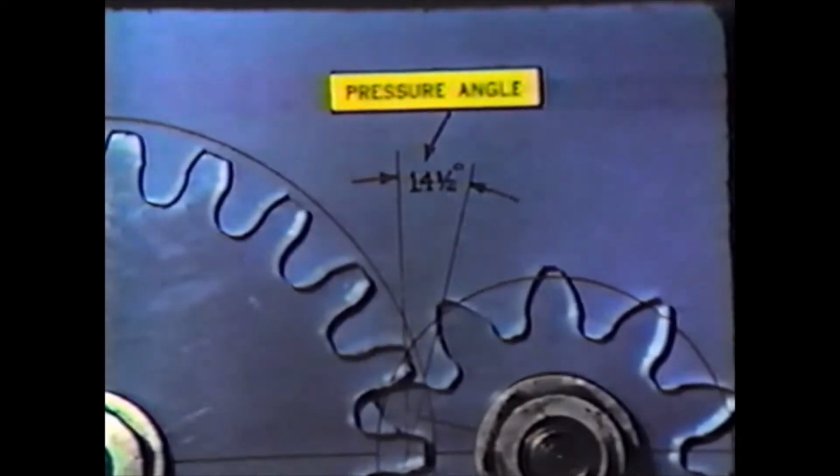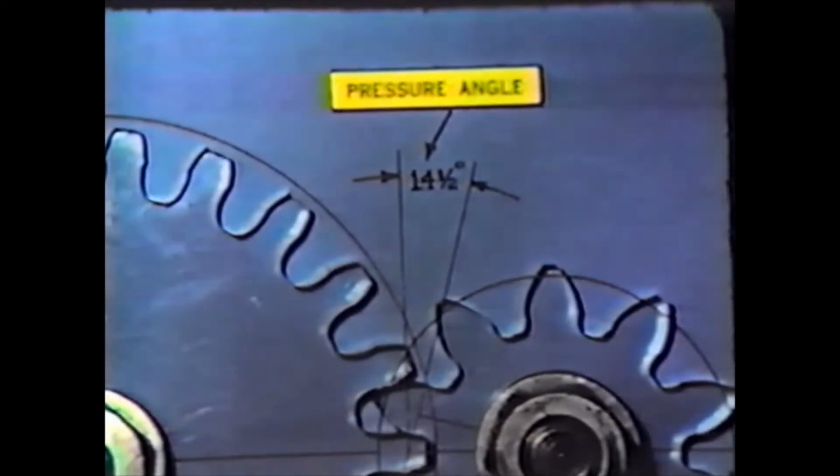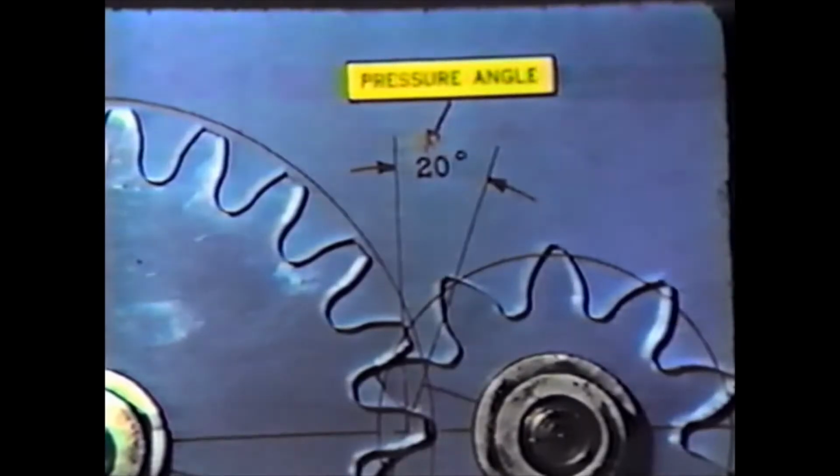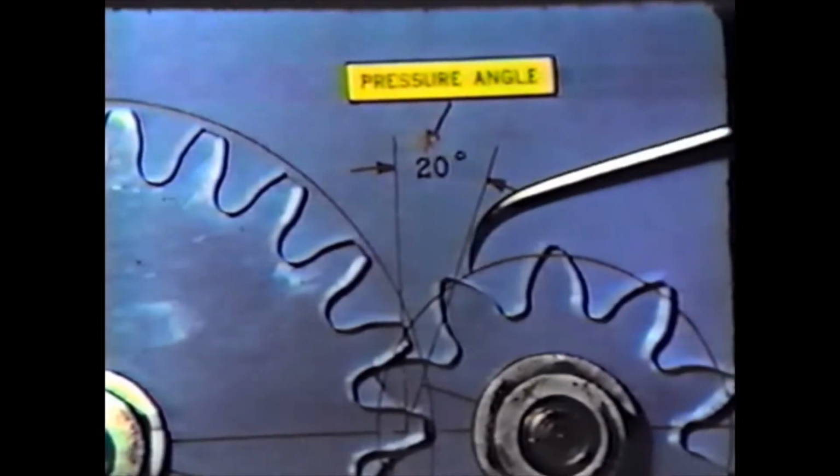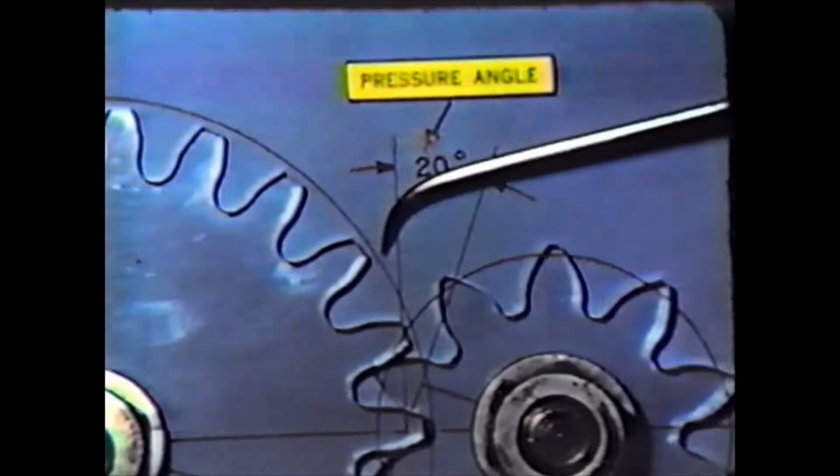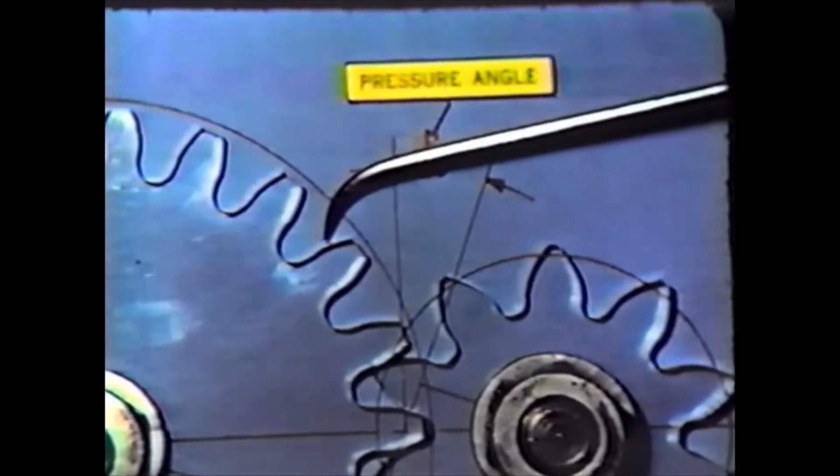Another method is to increase the pressure angle, maintaining enlarged and reduced diameters. This improves gear action by lengthening profile on the gear tooth. In some cases, an increased pressure angle alone enables standard blank diameters to be used.